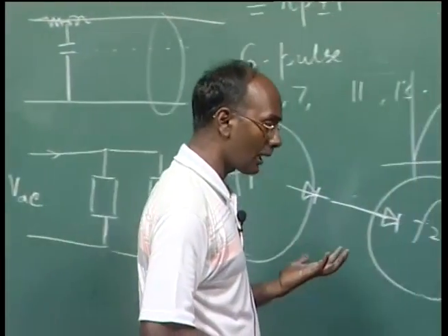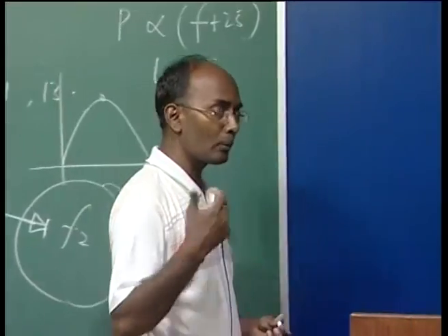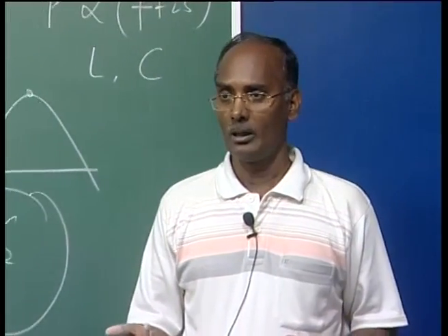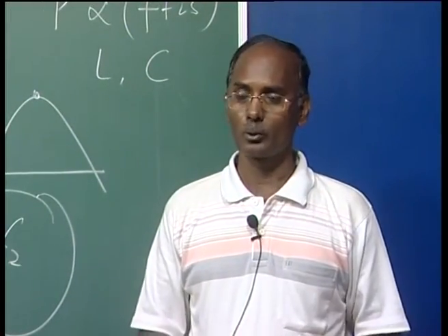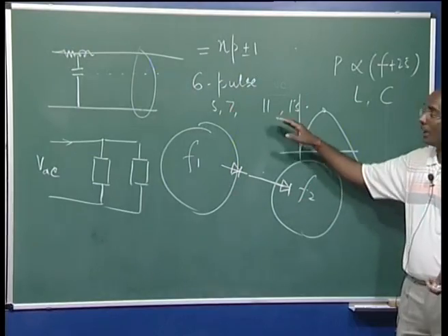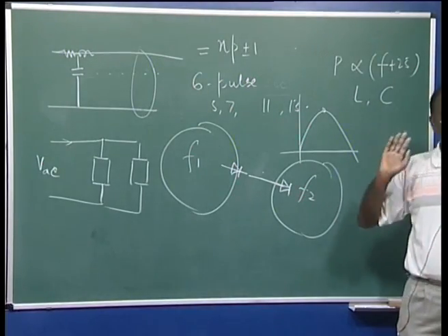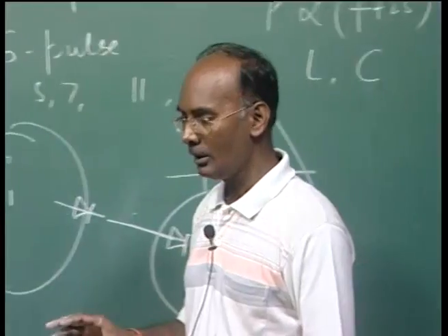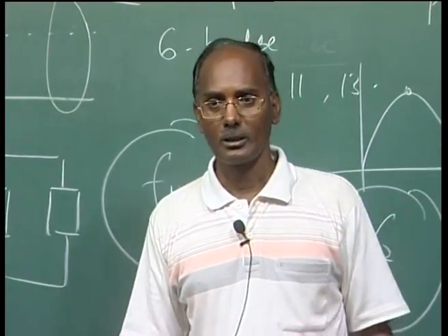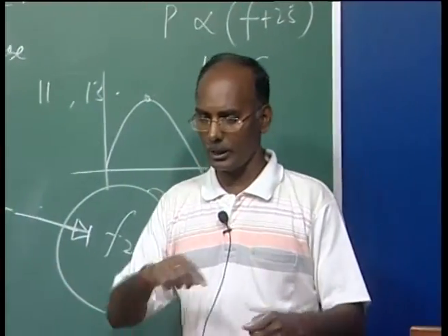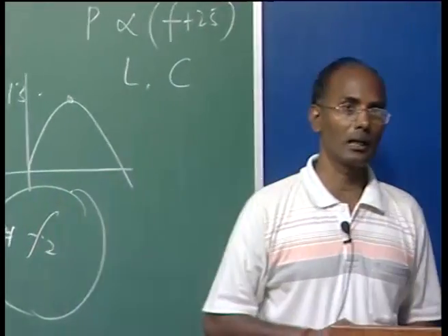So the introduction of harmonics leads us to go for the filter option, but it is not possible to filter out all the harmonics. We allow some of the harmonics to enter the system if the magnitude is less, but a perfect sinusoid is always better and desirable.